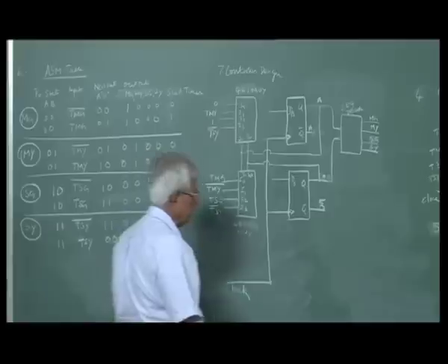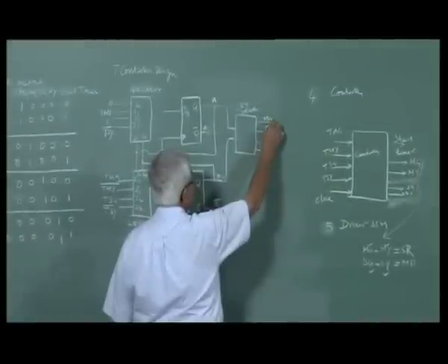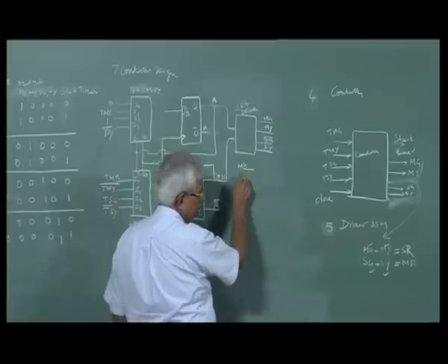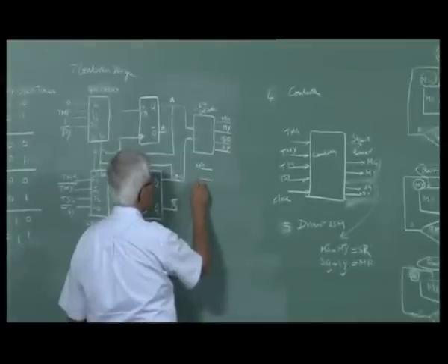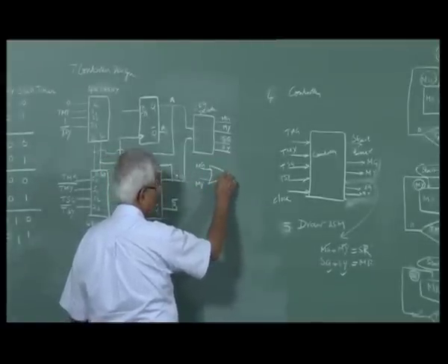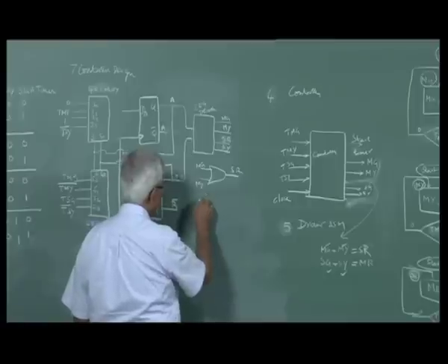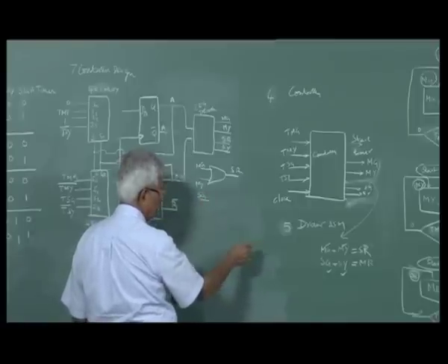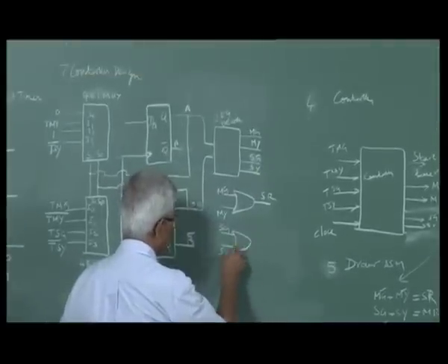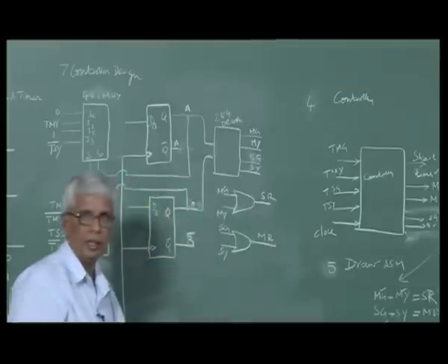We already said MG or MY gives you SR. So MG or MY, OR gate, side red. Similarly, SG, SY, OR gate, main red. So all the 6 light signals.